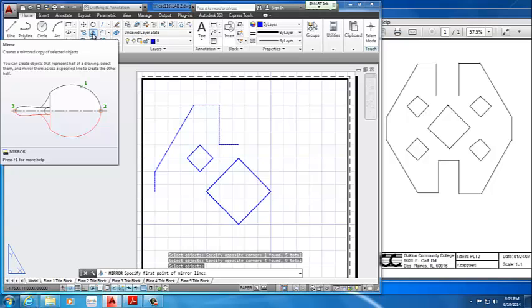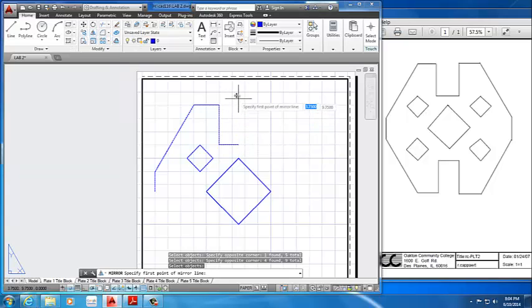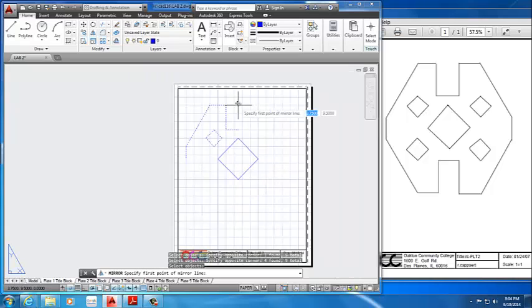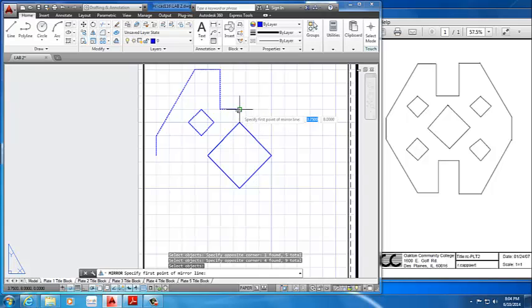So what we're going to do is create a line that's going to be centered. You can either guess that that's going to be the center, use the endpoint here of the line and go down, because that's how you're going to mirror it over, or you can even use the diamond shape as a reference. So you select it from the top or at any of this center line area, you move your mouse down and you'll see a somewhat of a demo of what it's going to be. If you have your mouse off to the side, it's not going to work. But if you have it perfectly 90 degrees, you'll see that it works perfectly.